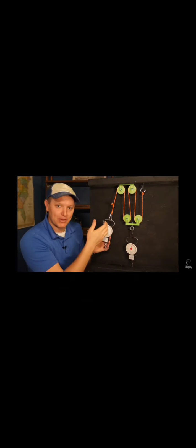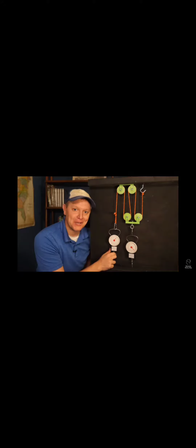This is the same number of ropes and pulleys and everything. It's just flattened out so we can see what's going on. So I've got a scale. I'm going to attach a scale to the input of the rope. And remember, if we put input tension, that tension goes all the way through. So as I pull here, I have 1, 2, 3, 4 ropes connected to the thing we're pulling. So if I put 2 pounds here, look at that. I get 8 pounds on the output. That's awesome. I'm getting 4 times the force, but I'm only moving it 1/4 as far.